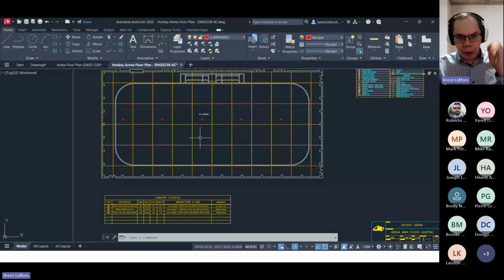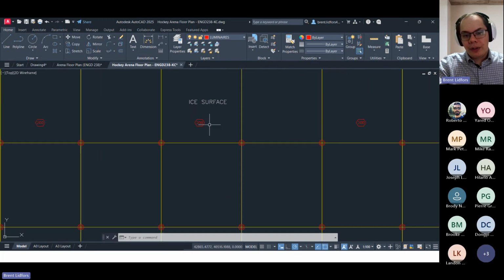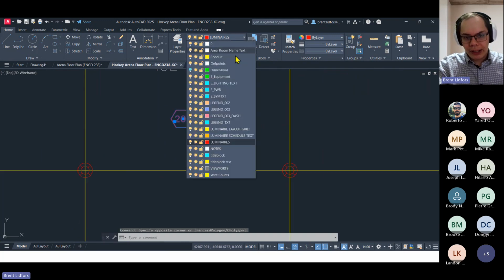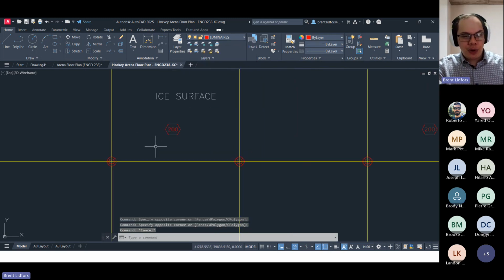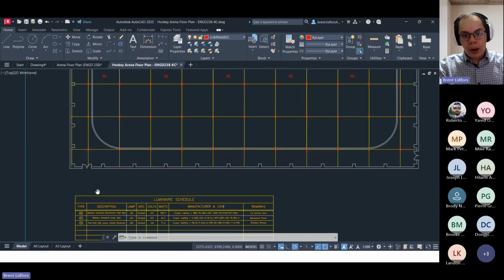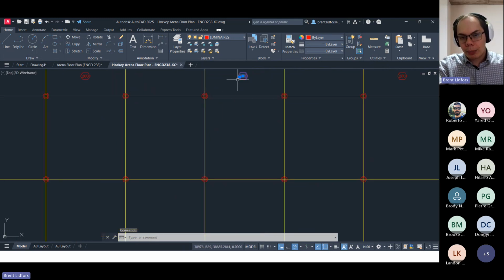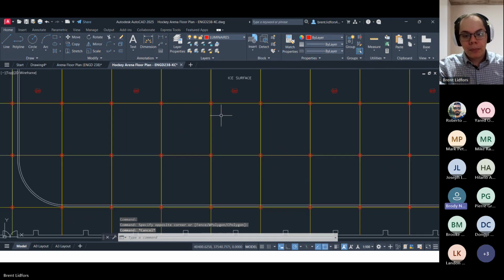Good point. What the sample has, and what I think should generally be done, is that the symbols should be on the luminaires layer, because they're associated with those symbols on the drawing itself. That being said, if you use the schedule layer, I'm not going to penalize you because it's not explicitly said in the instructions. Best practice would be to match it to the symbols it's trying to represent.